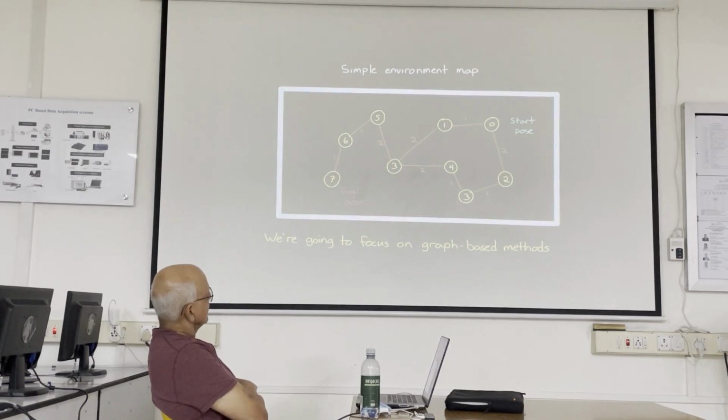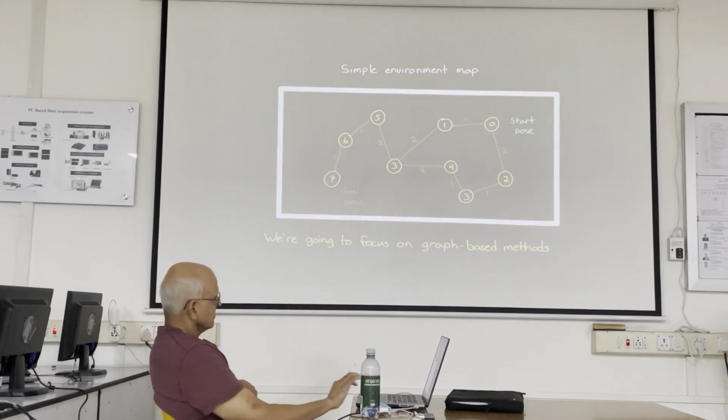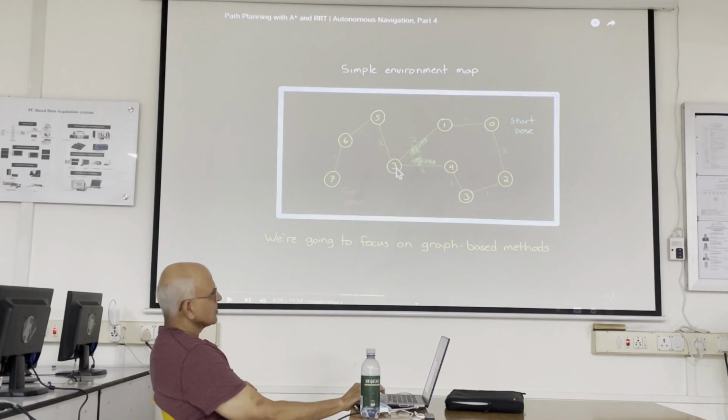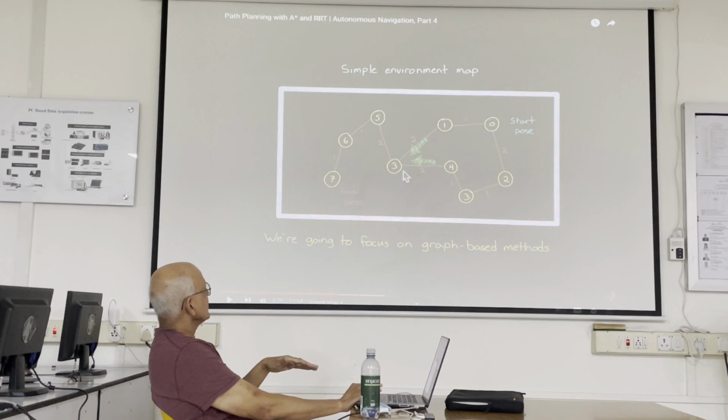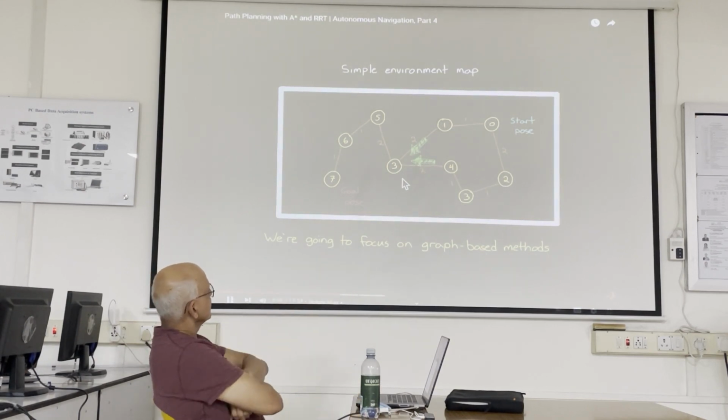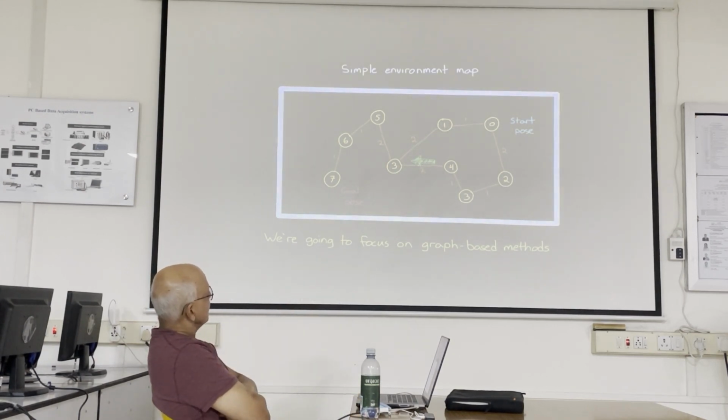A graph can have nodes connected in any way you want, but in a tree, each node only has a single parent. If you can get to a node two different ways, this node has two parents. Not good in path planning. So it doesn't make sense to keep the path that is longer if you're looking for the shortest path. So you can remove the edge for the longer path, keeping a tree structure. In this way, a tree would start at the location of the robot, and the branches would venture out to other states but never recombine.